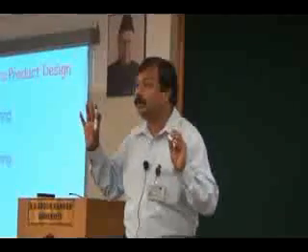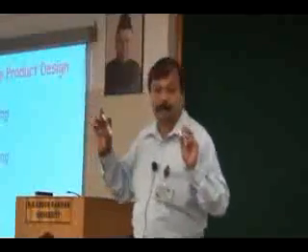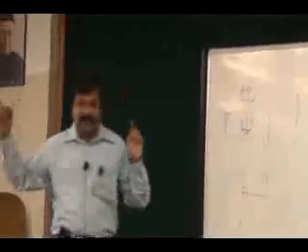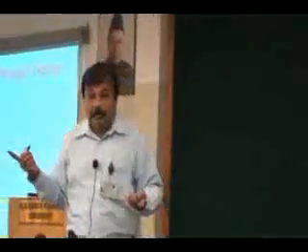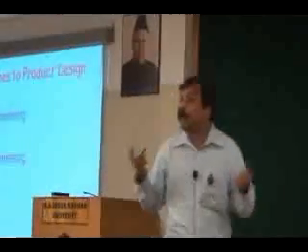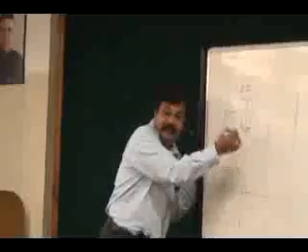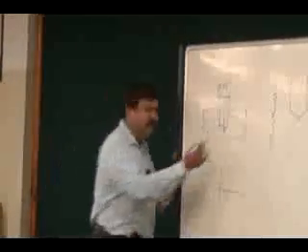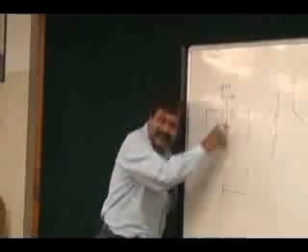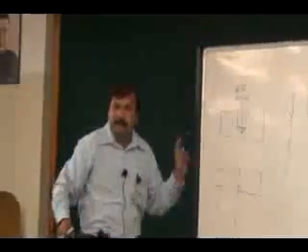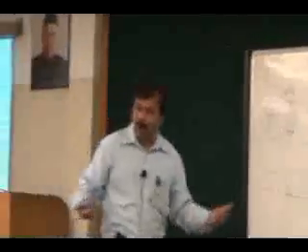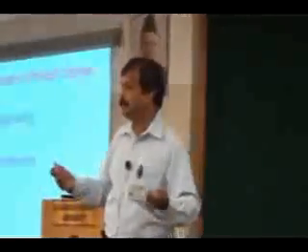That is the point I am trying to impress. The manufacturing man doesn't know whether such a conical end here is permissible or not, or should this drilling end here, or can it continue till the other surface? Can it be a through hole? A through hole will make it much easier.